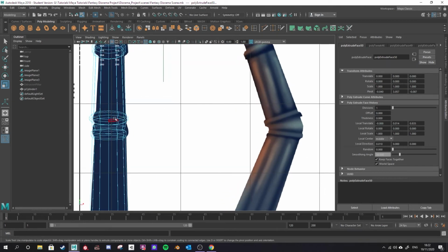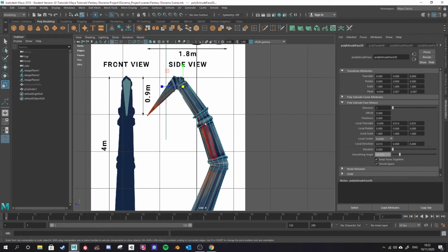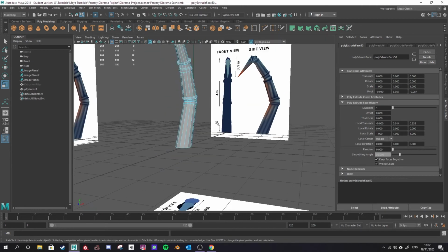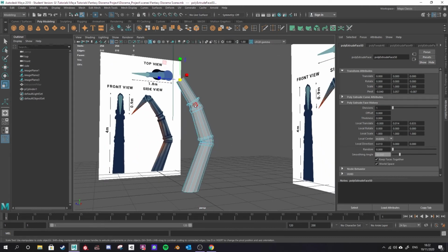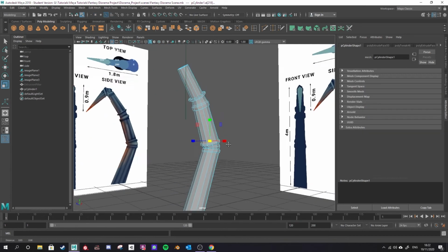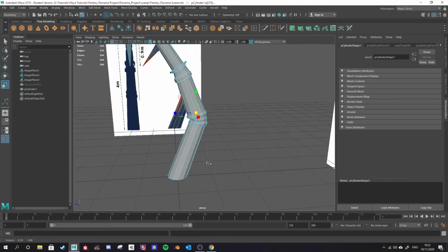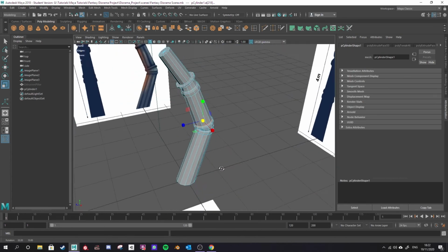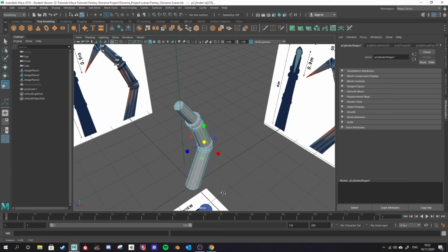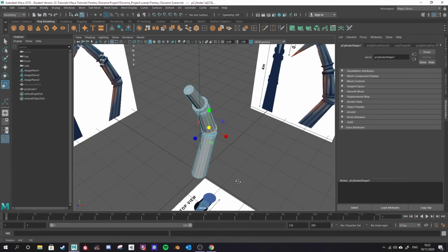You can see the way these circles are all overlapping each other, these extrusions are all overlapping, but from my side view I was able to model something accurately, which ends up in a better result here. It would take ages of rotating all of those different edge loops to have got that done from my front view extrusions. Okay, so whenever you're doing extrusion modeling, think about what the best perspective would be for each extrusion to make sure you get an accurate representation of what you're modeling. So all I was using there was the extrusion tool, G to repeat the extrusion, R to scale, and W to move each extrusion as I completed them.